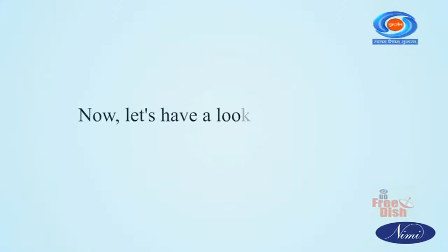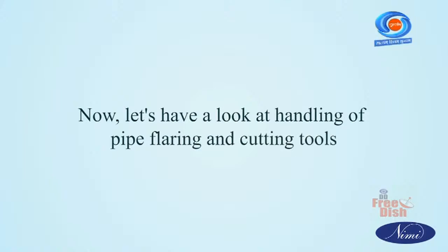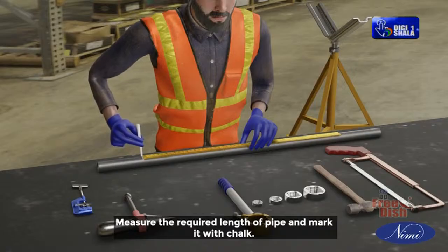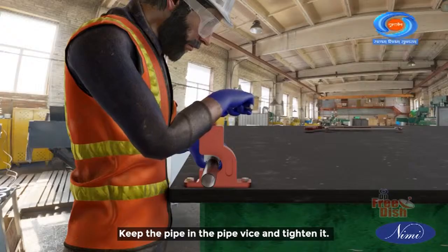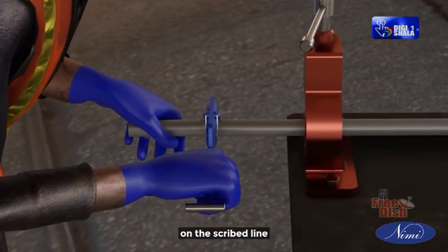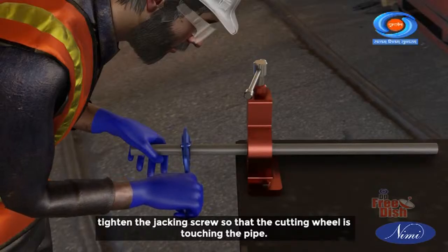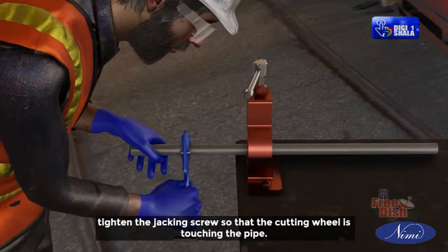Now, let's have a look at handling of pipe flaring and cutting tools. Measure the required length of pipe and mark it with chalk. Keep the pipe in the pipe vise and tighten it. Fit the pipe cutter on the GI pipe on the scribed line and tighten the jacking screw so that the cutting wheel is touching the pipe.